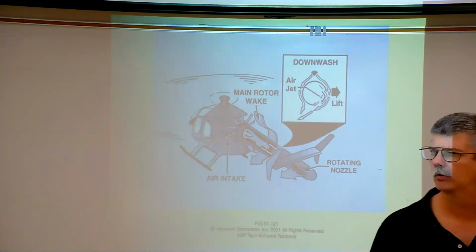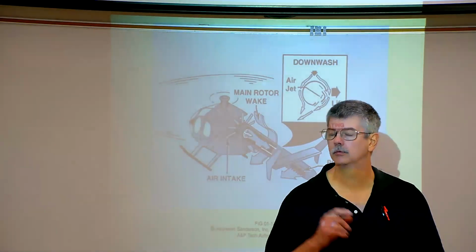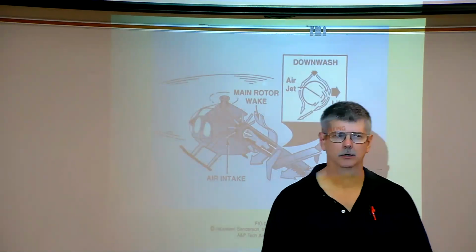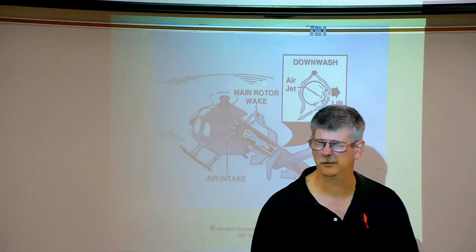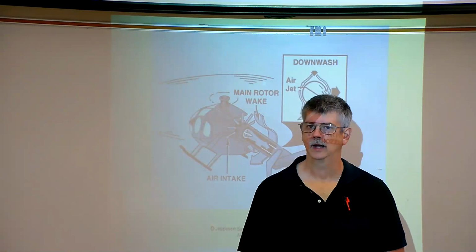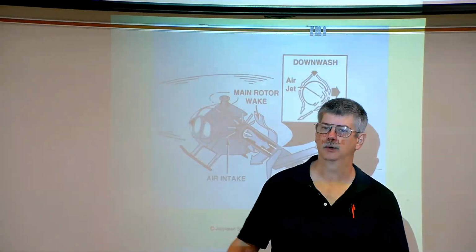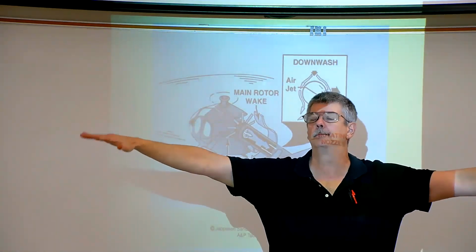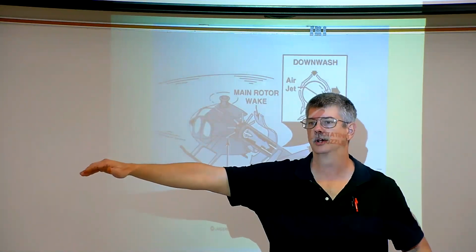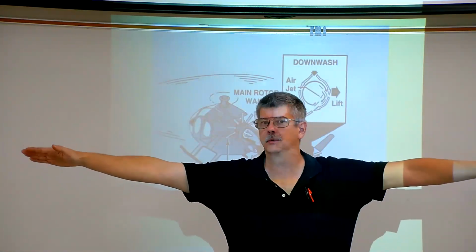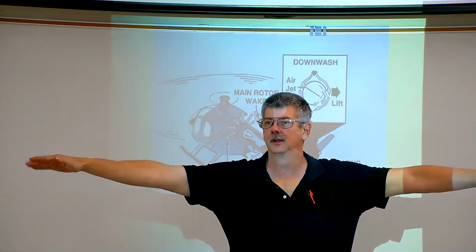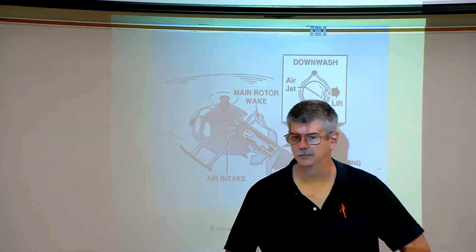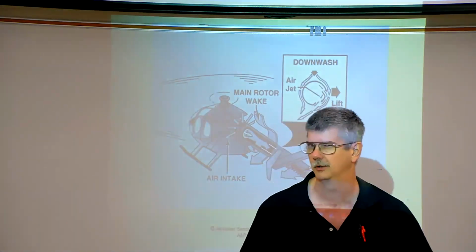Do they stop? No. Do they stop rotating in midair? No, no. I don't know how or what I said to make you think that. The collective is a way that the pilot, when they raise or lower the collective, it does the same thing to the pitch of the rotor blades. So if we pull up on the collective, all the rotor blades' angle of attack increases so that we go up. If we decrease it, then the blade angles decrease and thus we produce less lift.